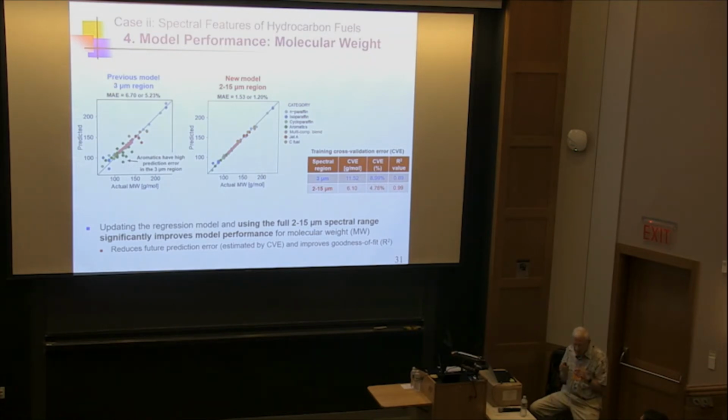And he observed that if we measured it at 2 different wavelengths, that ratio, not only could we use either wavelength for the amount of fuel, the ratio predicted the ignition delay time. That was the first time we realized we could learn something by looking at the spectrum. In any case, he used only 3 microns. So the new student uses 2 to 15.